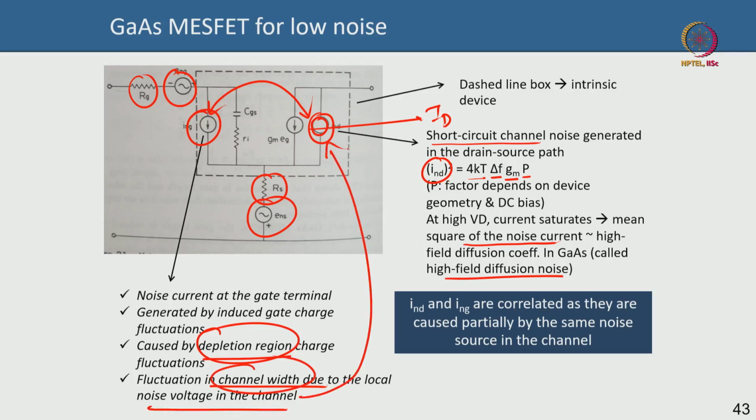So, the noise in the drain current, an inherent noise, basically makes the drain current fluctuate. That means the depletion width fluctuates, which means the depletion charge also fluctuates, and if the depletion charge fluctuates, then the charge that it mirrors at the gate terminal also will fluctuate, because the gate is mirroring the charge. Any charge that is fluctuating in the depletion channel will also lead to an induced fluctuation of the charge in the gate metal. So, there is an induced gate charge, and these are correlated to the drain charge in a way.